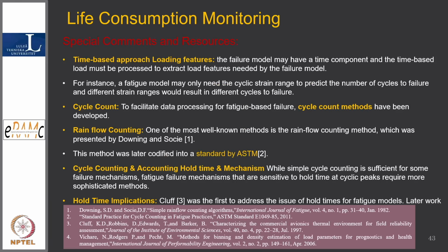There are some special aspects of life consumption monitoring. One is the time based approach to loading features: many loads in so many days, years or hours. The failure model may have a time component, and the time based load must be processed to extract the load features needed by the failure model. This exchange of information from time based to cycle based is driven by what you want to model, what information the failure model wants.